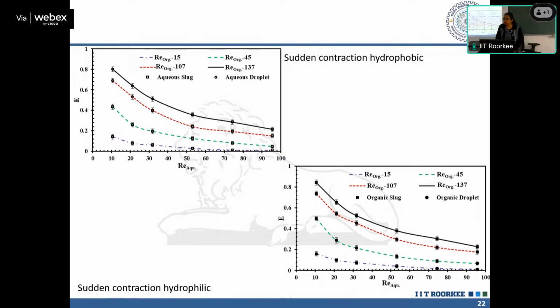Because then you have to see the possible combinations of wettability, because what always happens is that the reaction or mass transfer happens at the interface. Any disturbance wave production at the interface will enhance it. So you can think that the interfacial phenomena will benefit from any formation of disturbance waves. Now you have to see, between the G3 type of geometry or the G4 type of geometry, which one will be the beneficial one.